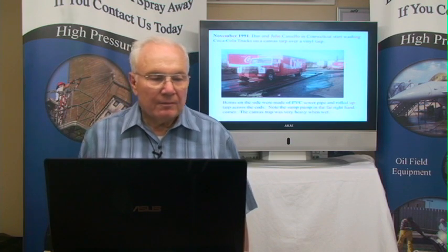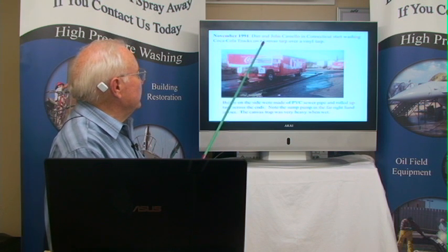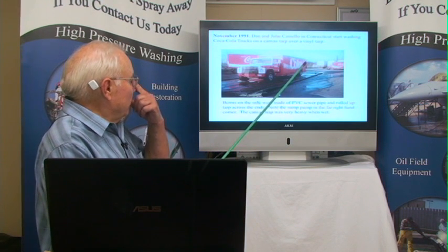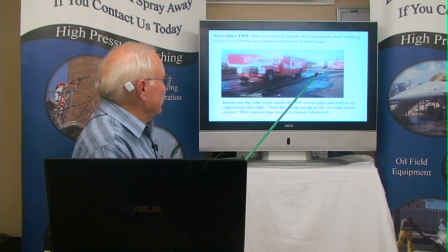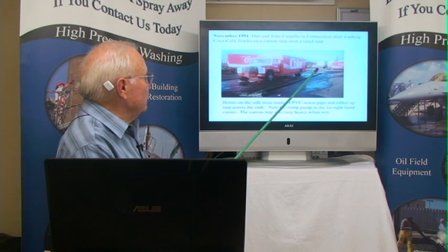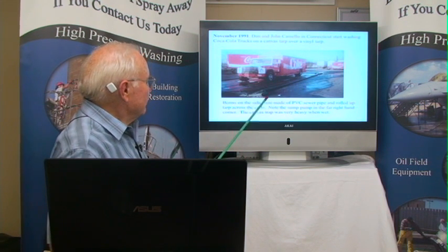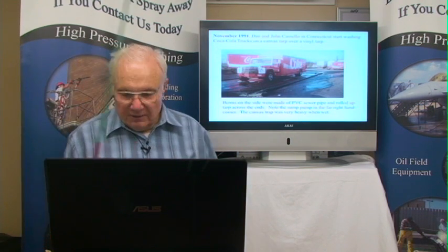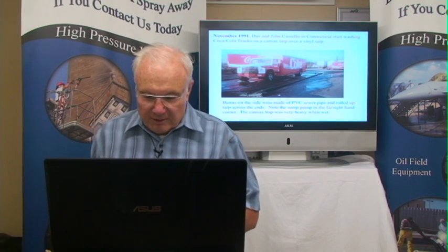This is the first time I personally became aware of somebody washing on a portable wash pit, which was in 1991 by Dan and John Costello in Connecticut. Pepsi-Cola got into effect. They had a sump pump down here that picked the wastewater up and sent it to the sand trap at that particular location. And they used berms made out of PVC pipe, and they made it out of a tarp material, so when it was wet, it was real heavy. Since then, those are almost always made out of a material that won't absorb water.